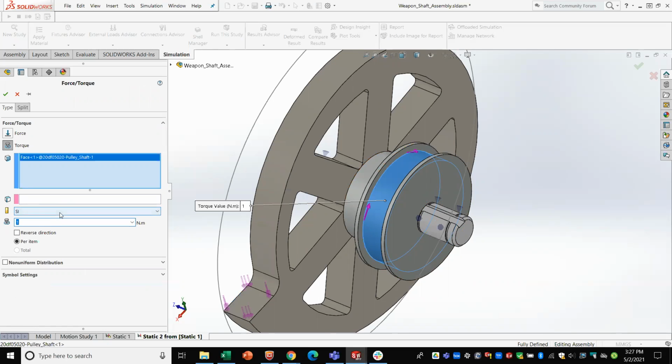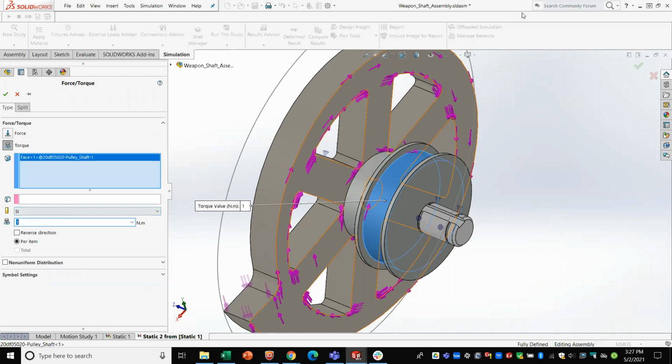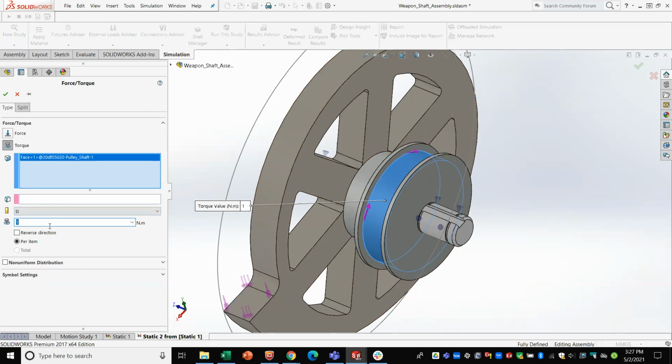And does anyone know what the torque that motor can output is? I think it's 5.57 Newton meters at stall. Okay, and what's your gear ratio? 2 to 1. Okay, so we're looking at basically 11 Newton meters, say? Yeah. Okay.